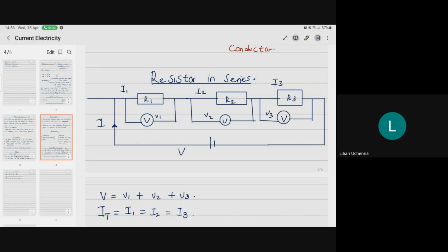Good. Resistance is increasing, isn't it? And the voltage is shared among the bulbs. Are you seeing it now? If you add the resistance together in series, the resistance is combining and increasing. R1 plus R2 plus R3 is increasing. And eventually the voltage is shared. And because of that, it gets dim, right? And what does it tell you?